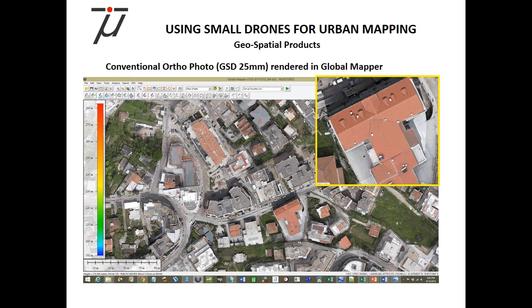So you can't always have a camera right on top of a building. So therefore, you will always see some fudge on the vertical surfaces on a conventional orthophoto taken from, say, 1,000 or 2,000 meters above the ground. Whereas here, there's virtually no sign of leaning buildings on the orthophoto. Next one, please, Oliver.